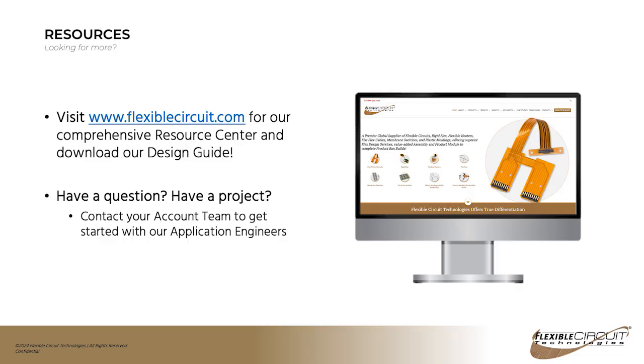With flex circuits, the bigger the panel, the more difficult it is to process them just because the material is so dimensionally unstable. It can grow and shrink by up to 1 mil per inch just with temperature and humidity. And what you'll find in Asia is because the material comes in rolls, it's typically much smaller panel sizes. So I would say that in Asia in general, you're probably looking at 250 millimeters wide by anywhere from 200 to 350 millimeters in length would be your standard panel sizes.